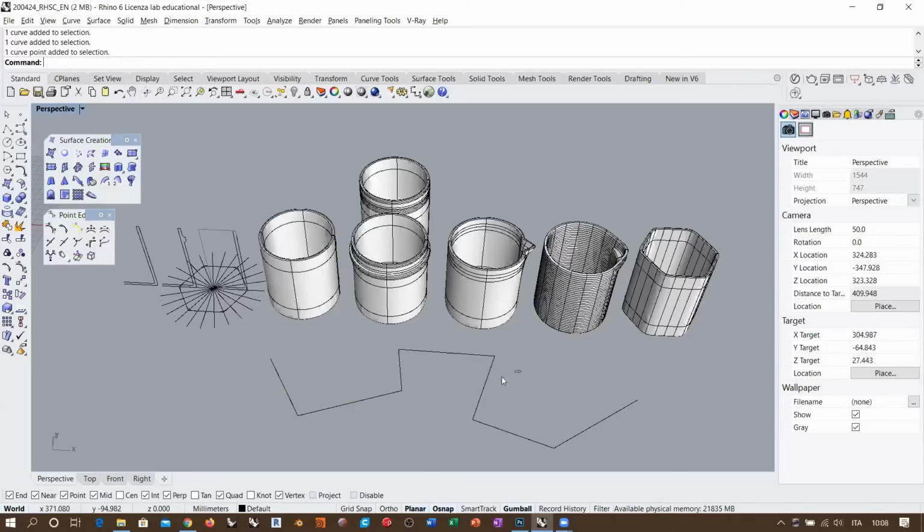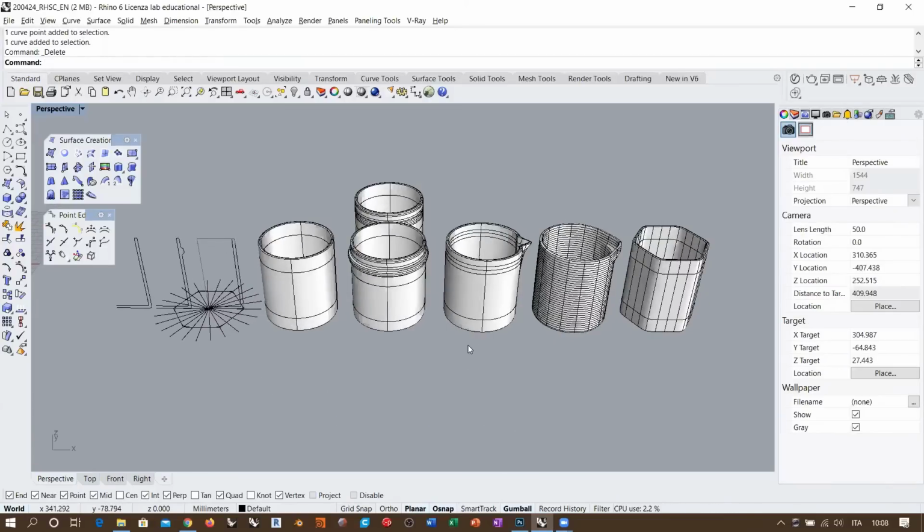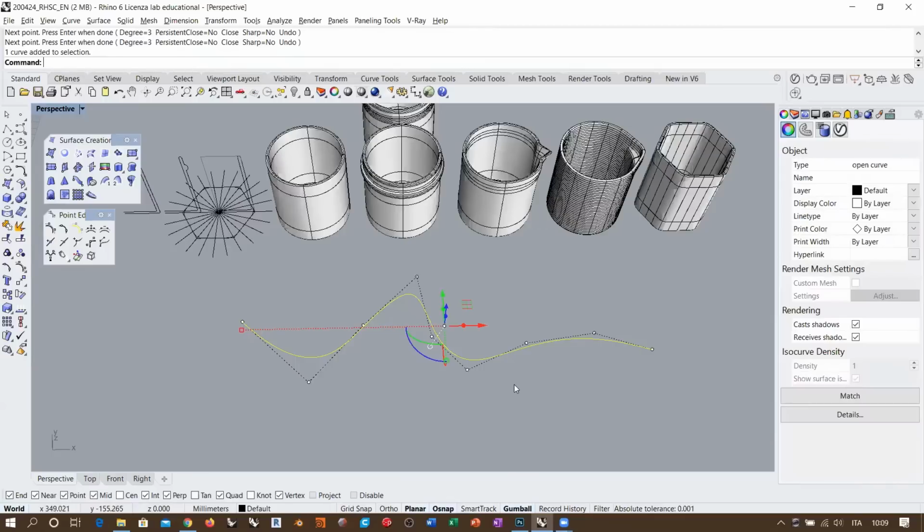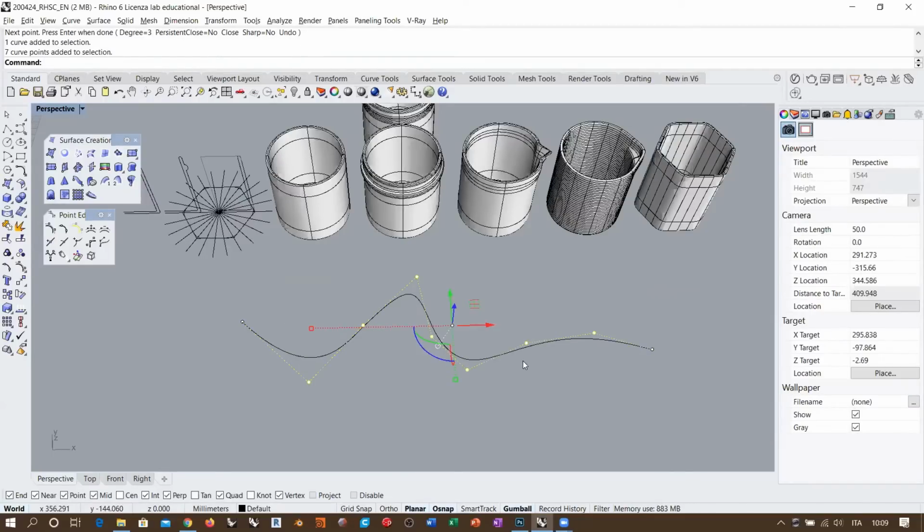But as for the rest, there is no particular geometry that by default has this kind of weird behavior. If you think about the standard NURBS curves or surfaces that you create with Rhino, let's do this with a curve, but it's the same with a surface. This degree 3 curve, as it has by default a uniform knot vector, won't have any internal kink. So by default, you cannot create an internal kink with Rhino directly. You can add a kink later on, but you cannot create it directly. You can do this with Grasshopper, but not with Rhino.